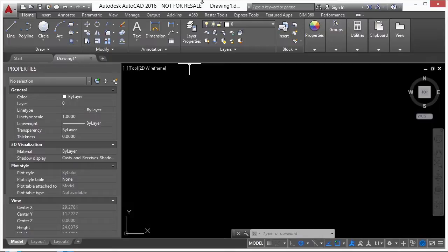Now, in two-handed CAD, users take advantage of the command line and the mouse, both. So you can turn off your ribbon even, you can turn off all toolbars, all menus, all palettes, etc., and you can still get to every command in AutoCAD through the command line. I'm not suggesting that's what you do. In fact, I use a bit of a hybrid method myself. I typically keep the properties palette open all the time because when I select anything, it gives me all the information I need or can work with on that and can manipulate it that way.